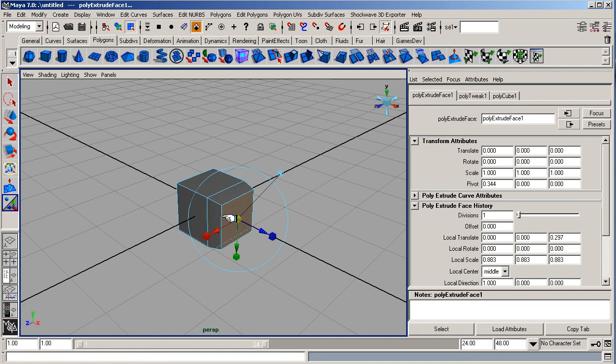Once you've finished doing what you're doing, if you press G, it allows you to duplicate the move. If I didn't do that, then I would be stuck on this. So I've duplicated my move by pressing G. I'll bring that out. I'll press G again, hit the square, bring this in, press G again, push it back on itself.